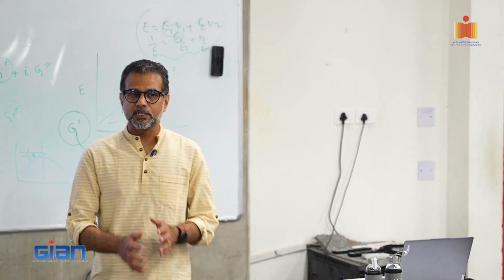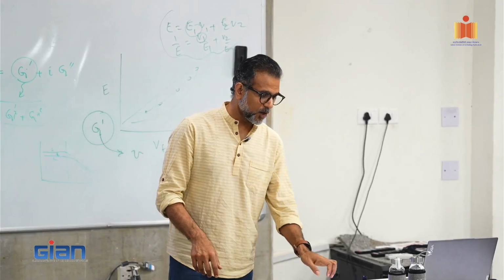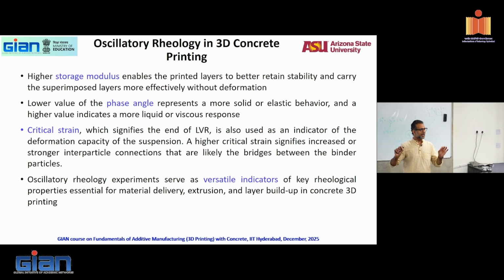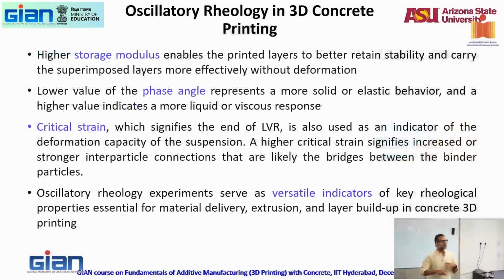All right. So we'll get into oscillatory rheology, or the idea of evaluating storage modulus. Yesterday we talked about applying a small oscillatory amplitude, right? A sine wave function at a very small frequency so that you are not damaging the structure of the material. You are just evaluating the material as it is.